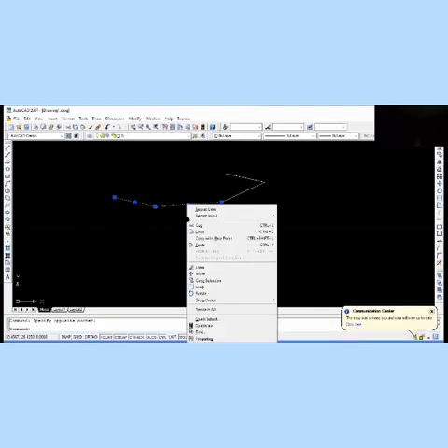And then when you right-click, you notice that the shortcut menus it produces are different from the initial ones. Here you can see we have additional commands of erase, of move, copy selection, scale, and then rotate, and other commands. So it is because you have what? You right-click, it is because you selected this one. That is why you have all these other shortcut menus.